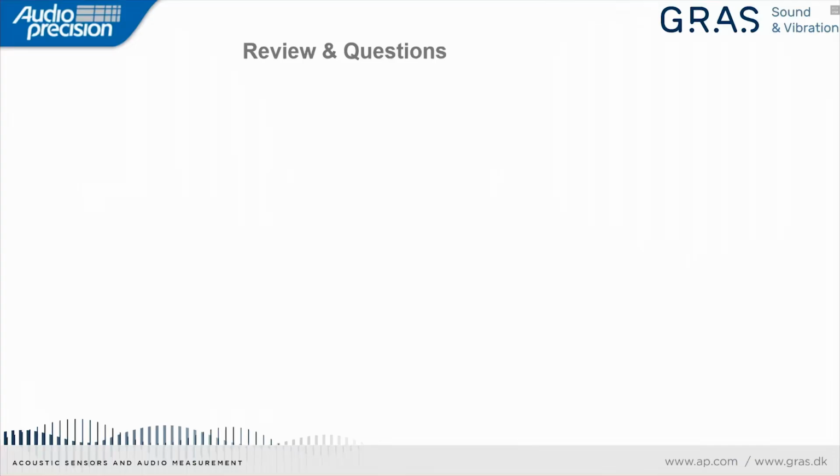Dan, I just had a question come through. Can you comment on when using a stepped or using a continuous sweep? Sure. That is a good question. There are some subtle issues there. So the continuous sweep is Audio Precision's implementation of Angelo Farina's exponential sine sweep technique, and it has a lot of things going for it. So the first is that it's very fast. It is unquestionably the fastest sine measurement technique currently available.